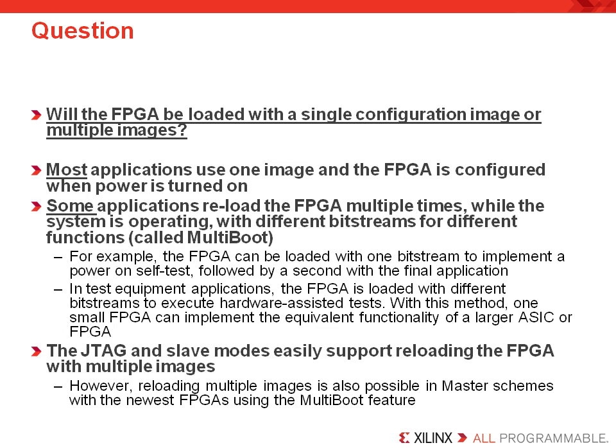Another question is, will the FPGA be loaded from a single configuration image or with multiple images? Well, if your application needs multiple images, there are some nice FPGA features to consider. The solution to this problem exists in Xilinx's newest FPGA families and is called multi-boot. This allows an FPGA to configure with different bit streams on whatever occasion the designer would like.